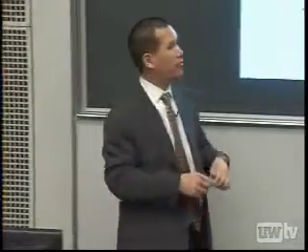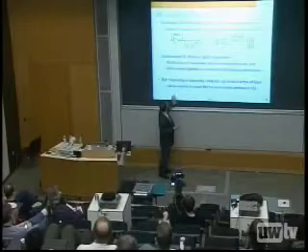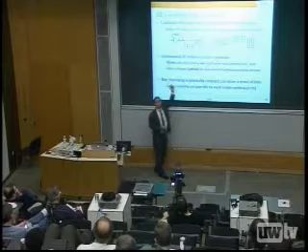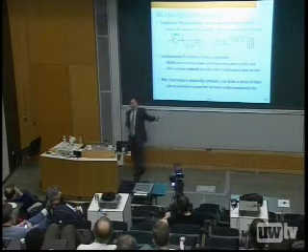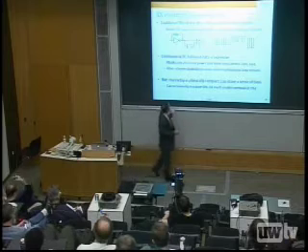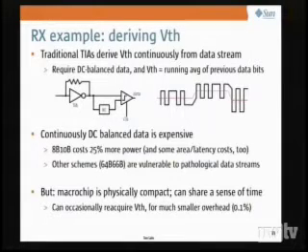Now, classically, for fiber line systems, the reference is often just an averaged version of all the data. It's the time averaged version of all your data bits running from 0 to 1, so that you can derive the threshold from your data. So that means that if my data moves up and down for common mode shifts, that's okay, because the average is still halfway between 0 and 1. Okay? So for any time I receive data, I just compare it with what the average has been, and that tells me whether it was really a 0 or 1.